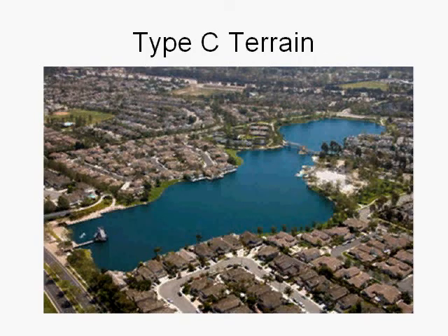In order to deploy OFDM and OFDMA systems, it is very important to understand the multipath environment and to actually calculate what we will call the large scale or macro effects like path loss and the effect of terrain on path loss, and also the microscopic effects or small scale effects such as multipath fading and Doppler due to motion.